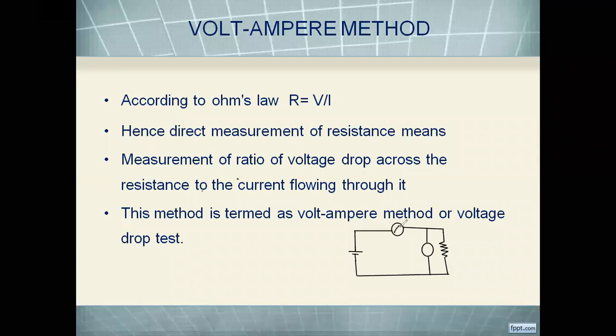This is the ammeter and this is the voltmeter. So you have given some voltage, and then you have a good deflection of the ammeter here and a good deflection of the voltmeter here. So we use an ammeter, a voltmeter and some variable voltage source. Now this is the resistor whose resistance value is not known.